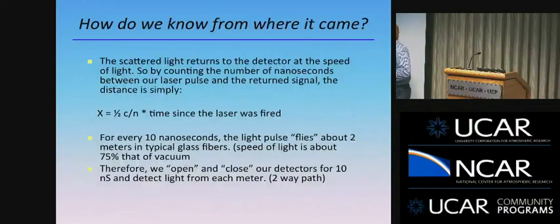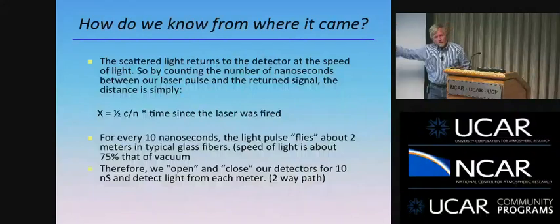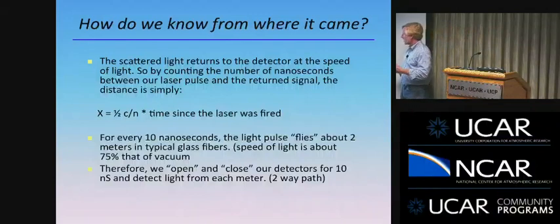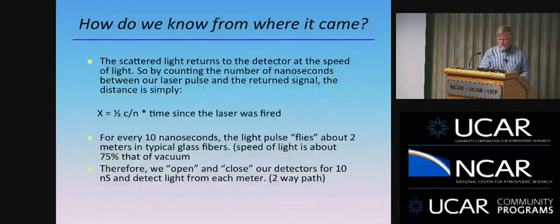Okay? And so I do that once. Then I open the detector again for another, let's say, 10 nanoseconds. Now I've interrogated the next meter of the fiber, anything that's gone down a meter, down 2 meters and come back. And I keep doing that until the light's all the way to the end of the fiber, and then I do that process again. Okay, so I'm basically accumulating photons all the way down. So it's no different than radar or atmospheric LiDAR, if you will, for particulate matter. Okay, and here 10 nanoseconds. These days, our systems are operating at 1 to even half a nanosecond.